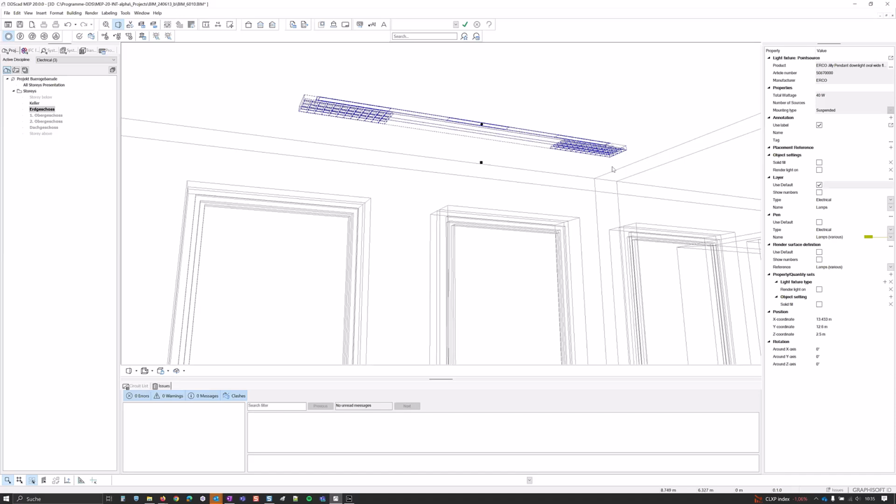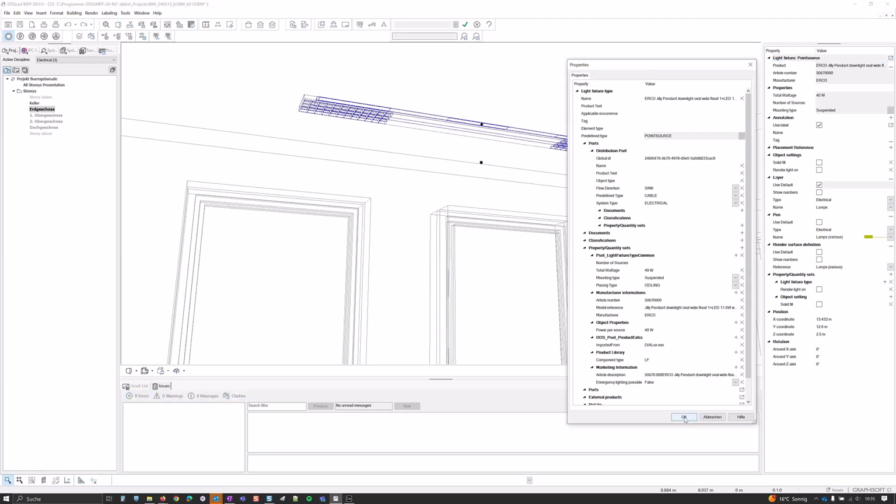And we see here in this property grid a few properties which were sent over from DIALux. So I can also take a look, for example, at the so-called type properties. Then we see even a few more properties. So that's a special window. So we have not only the short description, we have, for example, also the mounting type and everything else which is available. In addition, we see here also a port, and I will talk about this electrical connection port for cable a bit later.